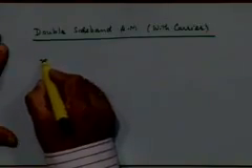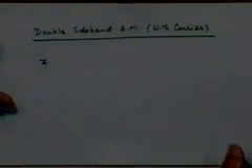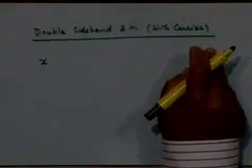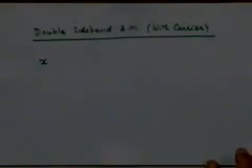So this is no longer suppressed carrier, we also put a carrier component in this. So basically, when generally one refers to amplitude modulation in practice, one is typically referring to this situation and not the suppressed carrier situation that we have discussed so far. The suppressed carrier situation was used earlier, in the earlier days, typically for transmitting data signals. For voice signals, this is one of the most commonly used forms of amplitude modulation, right?